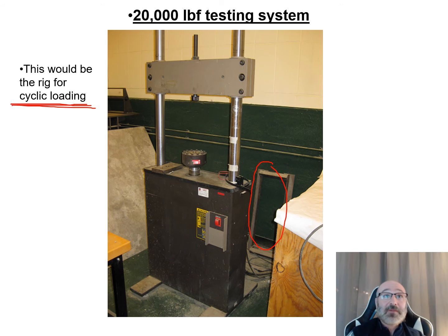So this is a great machine. Even though it's a uniaxial machine, the fact that it was capable of cyclic loading, and we could simulate what someone would see in a typical day of riding, was very, very useful. This was a great machine for life cycle testing. We could literally set it, program it to do this many cycles at this rate, at this stroke, leave it, and it's going to acquire the data at whatever data acquisition rate we programmed in. Walk away, come back, and take a look at the data and see, did it meet our criteria? How long did it last? All that type of information.